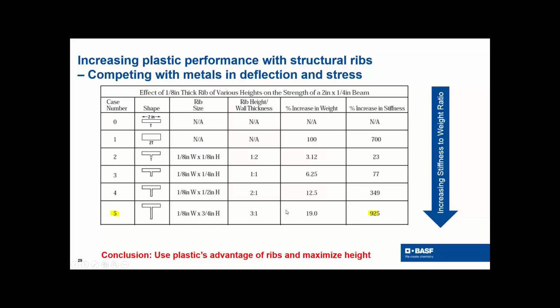So now you put that rib on there, and now the stiffness goes up 925%, so over a factor of 10. Huge, nice. And now with that rib, the weight and part cost went up roughly 19%. So you're much better. This one you could bring to the boss. In reality, maybe, depending on your application, you might go in between these two, or you may even go down a little bit, because even this one's 4 times as stiff as your original one.